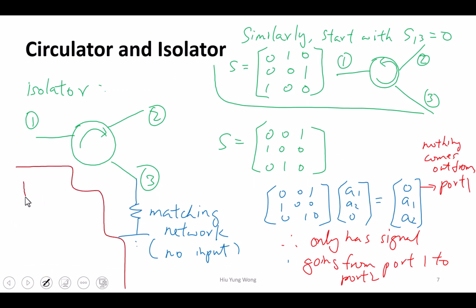You go in, you have a microwave signal, and then you want it to go into the qubit, or the resonator, and then you want this one to come back to the readout circuit. Then what do you do? You cannot just connect it, because this signal will leak out to the readout circuit directly, right? So what we can do is put a circulator here, so that this signal will go into the qubit, and those reflections from the qubit will go out to the readout circuit, right?